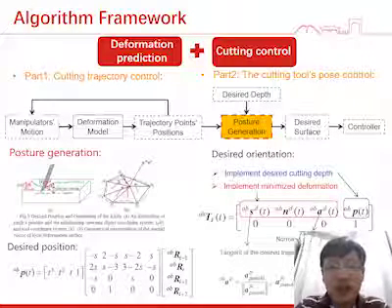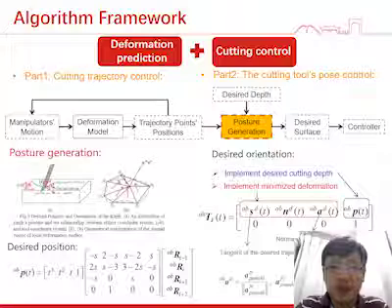According to the current position and orientation of the knife, the current homogeneous transformation matrix of the object frame with respect to the knife frame K is T, while S is the unit tangent vector of the desired cutting trajectory. A is the normal vector of the local deformed surface, which can be obtained by the pseudo-normal vector.